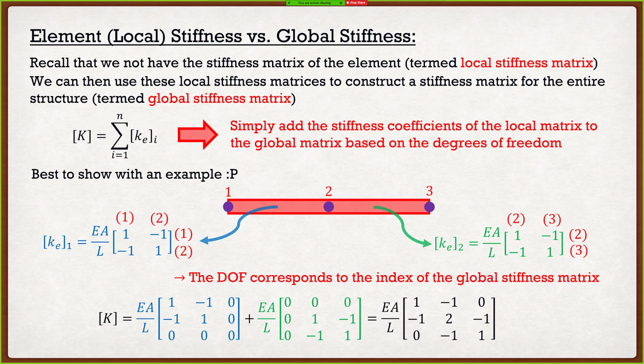And the reason why is because when we're dealing with these bar elements here, it's very easy to see a sequence where we go from node 1 to 2 to 3 to 4, all in a nice linear line. If that's the case and everything's in a nice linear line, then yes, we're going to get a very easy to determine matrix. But remember that another word for these bar elements is truss elements.